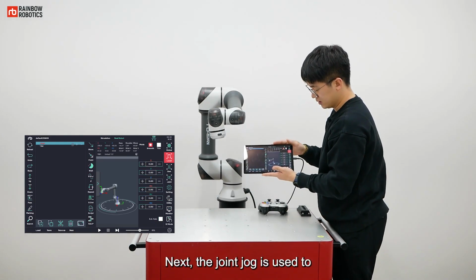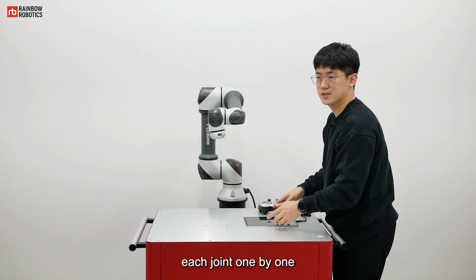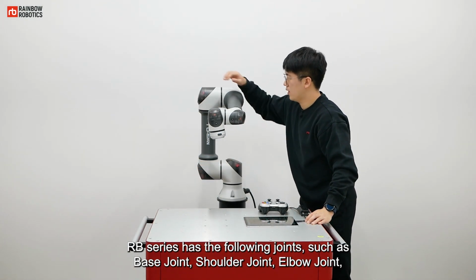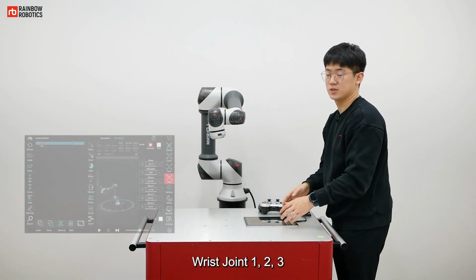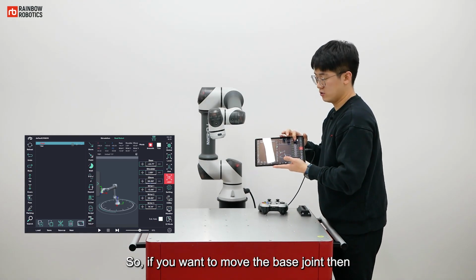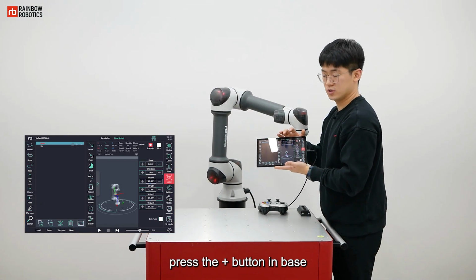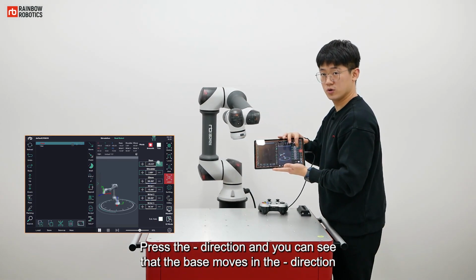Next, the joint jog is used to move each joint one by one. The RB series has the following joints: base joint, shoulder joint, elbow joint, wrist joint 1, 2, 3. So, if you want to move the base joint, then press the plus button in base. Press the minus direction and you can see that the base moves in the minus direction.